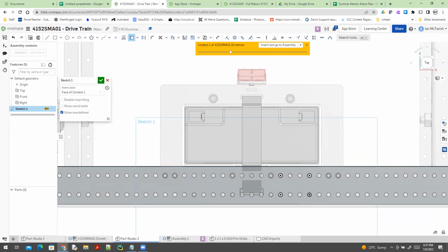I'll just mention, you might not realize what the use tool is doing there, but it's pulling the geometry from something else. There's a circle in another model. So when he clicks that circle, it's making an exact copy of the circle in the model you're working in. And that's where it's so useful.